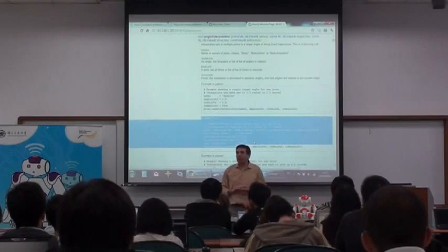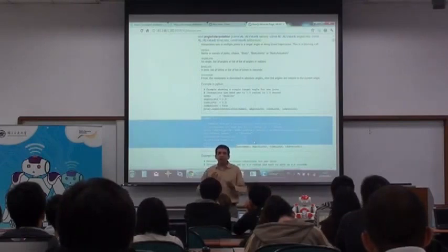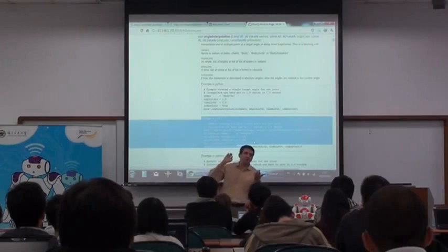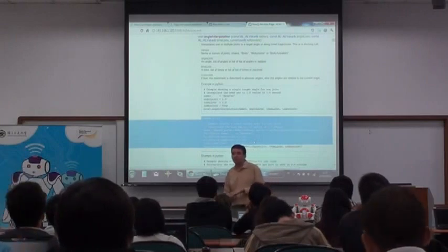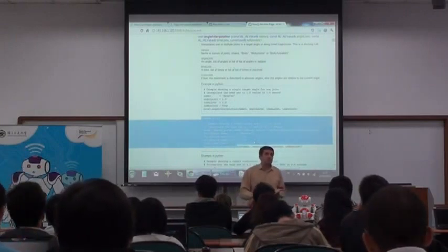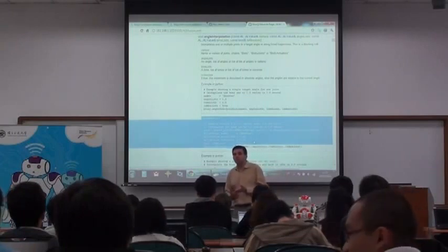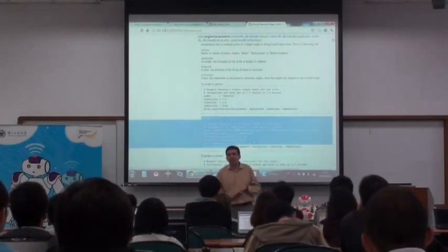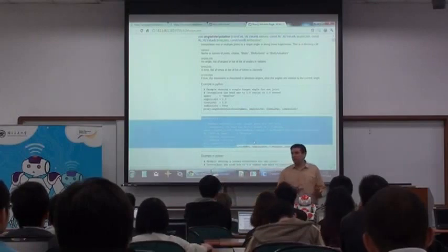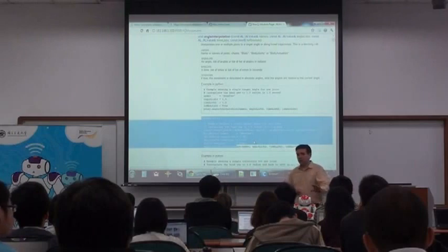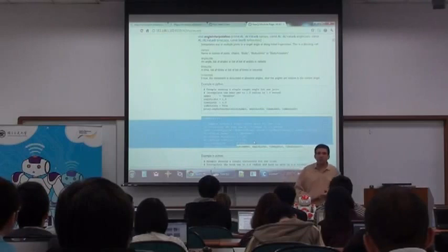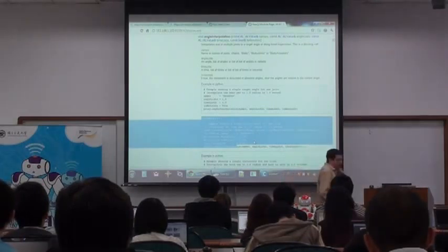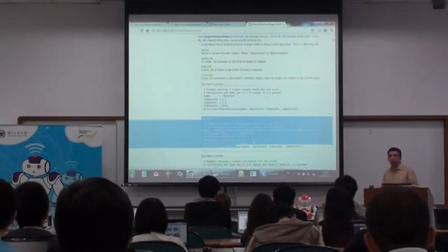You can also program the robot remotely in Java, MATLAB, and .NET. .NET is C#, etc. And I think that's all. But Java, MATLAB, .NET is only for remote programming. That means a program that runs on your computer and connects to the robot. If you want to have an autonomous program running on the robot, you can only do it in Python or C++. Also Choregraphe files, but Choregraphe is mainly Python processes, Python script.